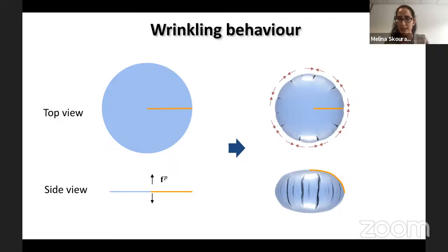You also have this phase invariance when you rotate the wrinkles. This translates into singular values in the Hessian of the energy of the system. In addition, you need very high resolution meshes to resolve the wrinkle geometry and to correctly predict the global shape.